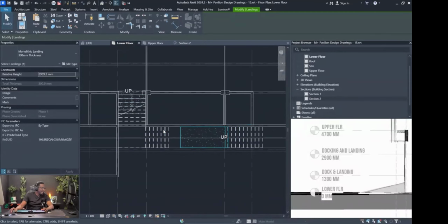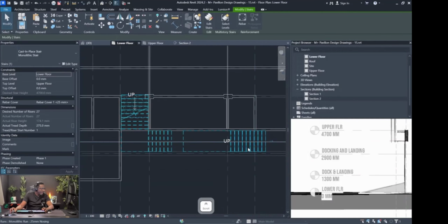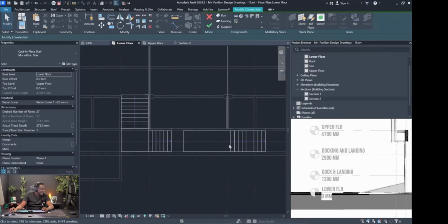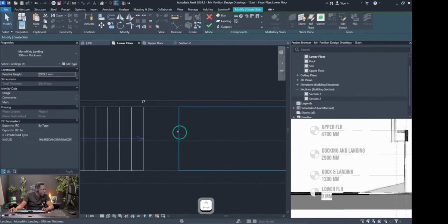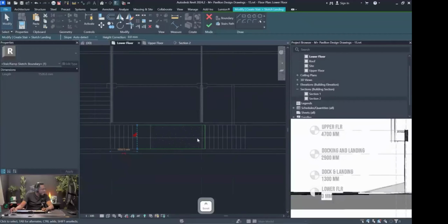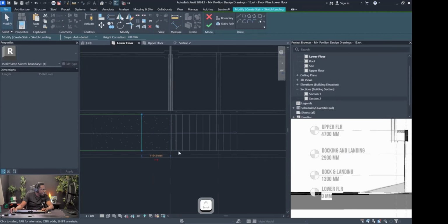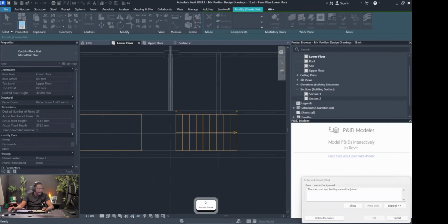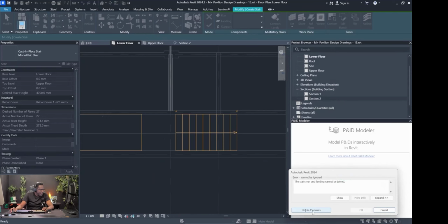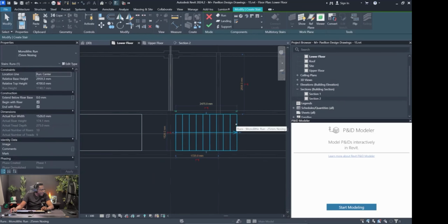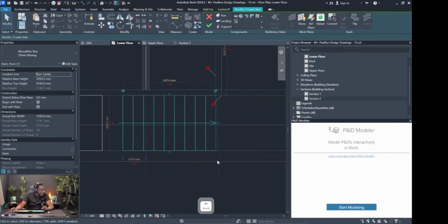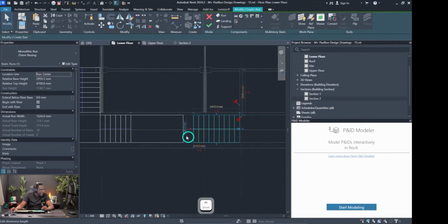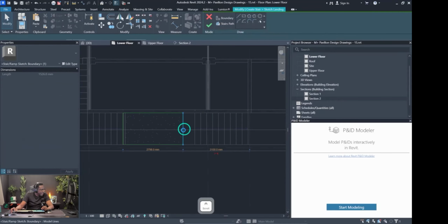Now, of course, I'm going to have to go back into the lower floor here, and I'm going to have to edit the stairs, and let's put this back to here, edit the sketch, carry the sketch there, and then we need to carry this actually back here. We're going to choose OK, and it's going to say that it has to unjoin it from right here. That's okay, because what we need to do is to drag this stairs back to the floor. And then we can go back and tweak the landing to make it back to the step. All right, so let's choose OK.